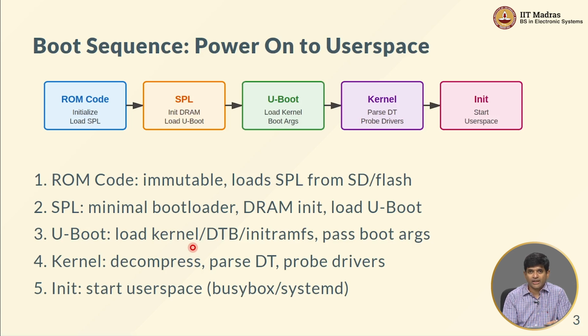Now in our Renode demos, we saw that we would basically say load ELF, and it would take care of taking the ELF file and putting it into appropriate locations in memory according to the code and data segments and so on. U-boot does that on real hardware. So it loads the kernel into appropriate locations in memory. It also loads the device tree.